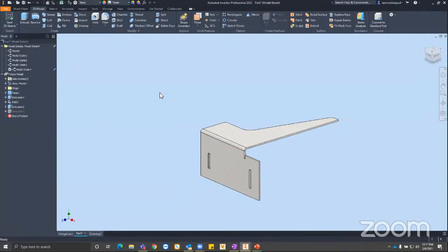Okay. That's a great question. I appreciate it. Yeah. To me, honestly, model states really feel like design views, right? If you're in an assembly and we create design views as opposed to level of details, you can pick or choose what components are being shown in any given state. It feels like they've incorporated that into models, and now we're leveraging features instead of components.